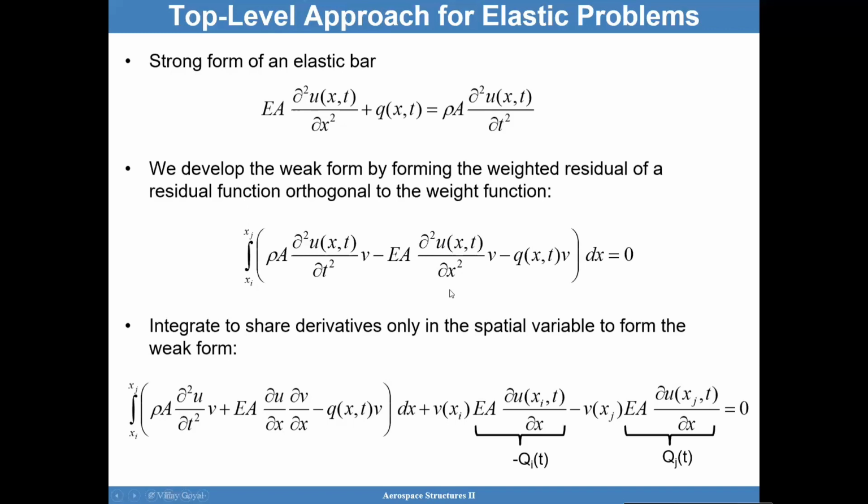That helps us because suppose for a second I want to approximate this deflection u with a linear function. If I do that, you can see that the second derivative of a linear function goes to 0. And I want to be able to approximate solutions with a linear function because I think that's not a bad approximation. As a consequence, by integrating by parts, we have weakened the continuity requirements. Now the derivative of a linear function u gives me a constant, so it doesn't go to 0. And I retain the ability to use an approximation for u as a linear function.